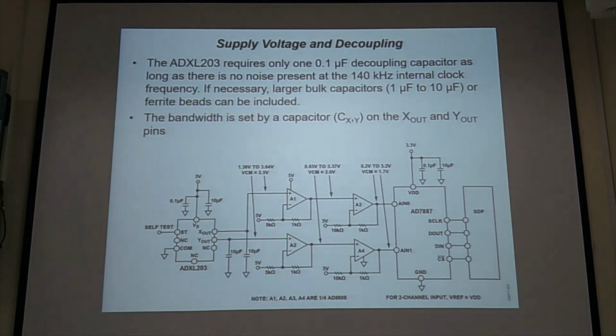Okay, to remove the high frequency AC signal, because we just need the DC signal. Because for the power supply, we only need DC. We don't want AC power inside to get into the power supply. So we have two capacitors to remove the AC noise.